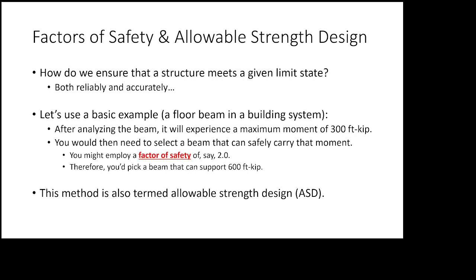Okay. And how do you rip the tab off that can very easily? Take it, and after a while, it kind of gives up, doesn't it? The tab just sort of gives up. Now, if you were to take a microscope and look at what you're doing there, you're introducing micro cracks in that joint. And the more that you do that, you start opening those cracks up a little bit more. So you start reducing the cross-section that can resist that load. And over time, those cracks propagate, they grow and grow and grow, and they go. That's a concept in a metal phenomenon called fatigue, right?